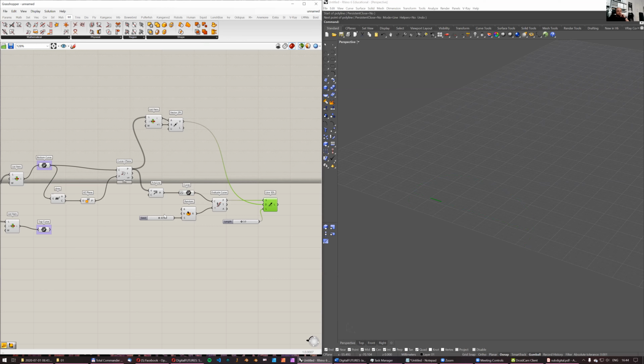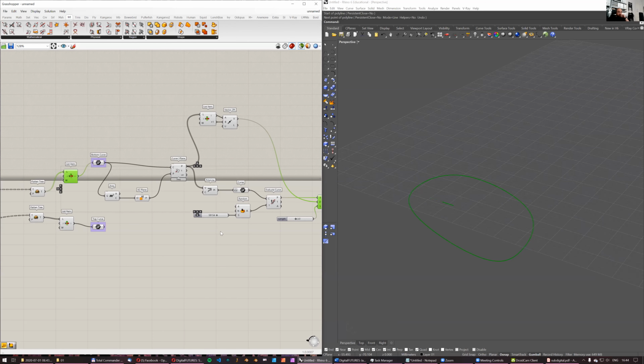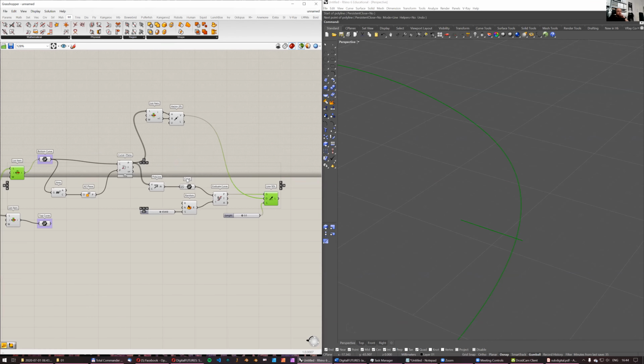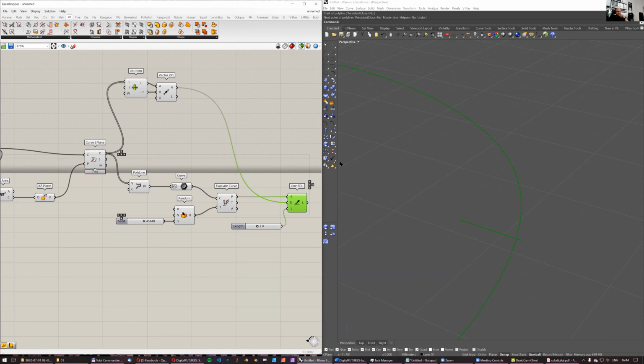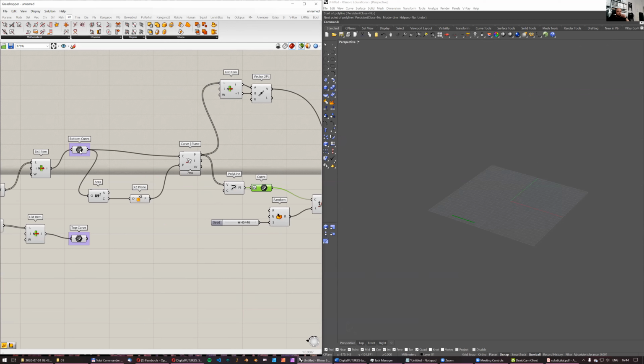The problem is that if this random value just randomly jumps outside, like if it's way too close to the edge, it could happen that the line will be outside of that curve, like here, you see, because I'm not checking where I am. So before I evaluate the curve at the random point, I need to make sure that it's 3 units shorter than it was at the end. I will chop off the last 3 millimeters, so that the random start of that leg should happen anywhere between here and 3 millimeters from the end. And if it jumps to the end, it reaches the very end.